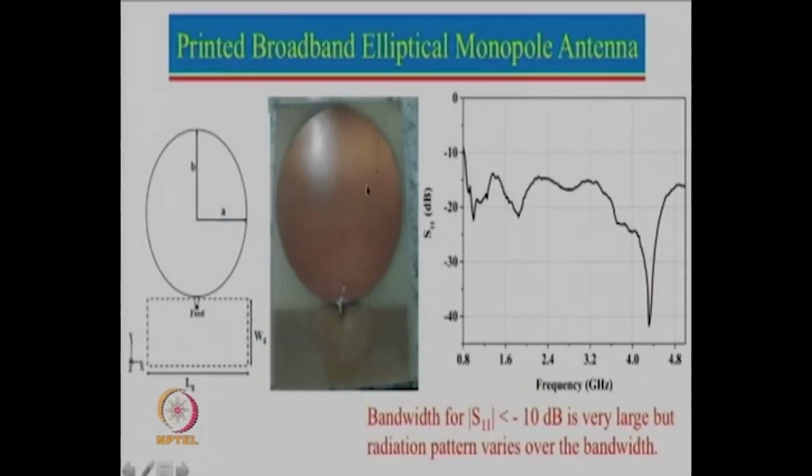But before we move there, I also want to mention that a lot of things are coming on the UWB band, which is from 3.1 to 10.6 gigahertz. First of all, this is the band approved by the FCC. This band is not approved by the Indian government, and the counterpart of the FCC in India is the WPC, Wireless Planning Commission, which comes under the umbrella of the DOT, Department of Telecommunication. So, you can do a Google search, say WPC DOT, and download their document.